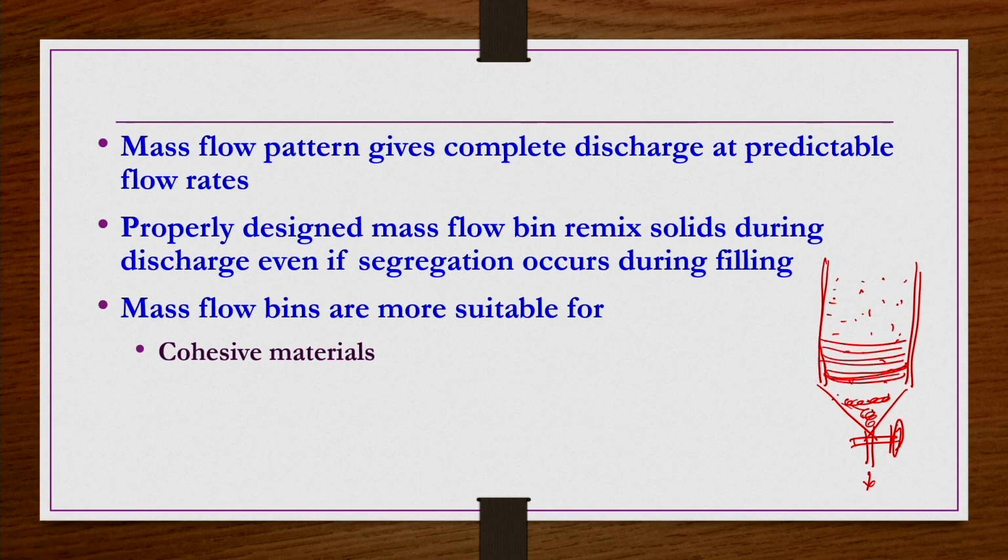So whatever the material in this bottom portion is, that has been taken away, has gone out of the container. Because of the sticky nature of the material, bridging of the material will take place, and those bridges are so strong that they can uplift the weight of the material resting on them. So that is a big problem with cohesive material.